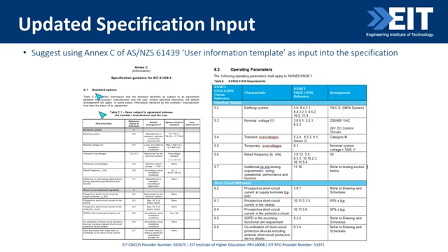So what we always suggest, if you are on the designing end of engineering, is that you want to specify what type of switchboard you want to use. As an example, I've put up here a reference to 61439. That's both an Australian standard and an IEC standard. It requires you to outline everything you want that board to have, from earthing, voltage, transient or temporary overvoltage limits, what frequency it should operate at, so all those technical specs so that your board can be built to suit your installation.